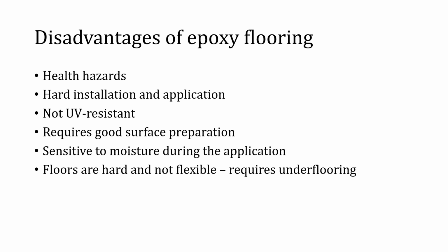Resin floor systems that are applied improperly could result in delamination, chip and peel. This unwanted outcome is typically caused by poor surface preparation prior to the application of the final floor finish. Another type of floor failure is the occurrence of air bubbles or blisters in the resin flooring. This type of failure may be caused by too much moisture in the substrate.